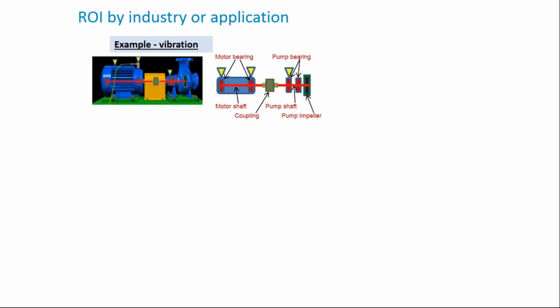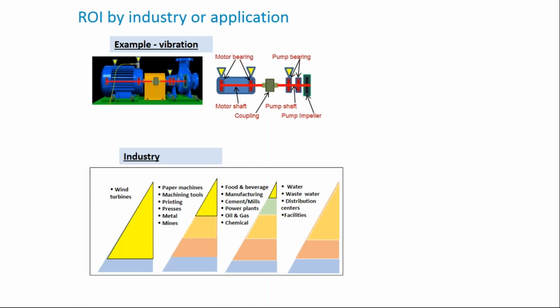Now, from a vibration standpoint, rotating machines just aren't that different from each other. I know that a lot of people feel their machines are very specific and very unique, but when you're looking for the common faults on a rotating machine, every machine really is the same thing. It's a rotating motor shaft with a couple of bearings, a rotating pump, fan, compressor with a couple of bearings, and then a coupling or a belt in between. When you're looking for imbalance and misalignment, that's really all a machine is from a vibration standpoint.